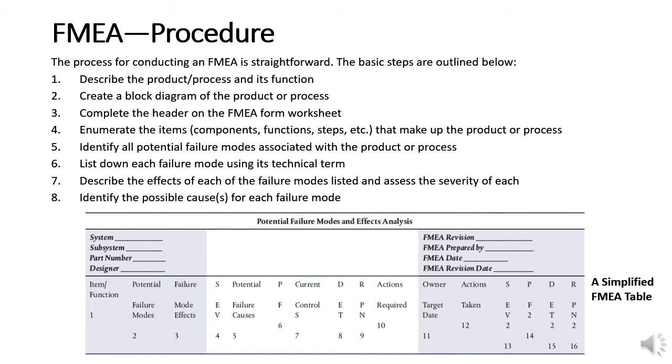A failure mode is defined as the manner in which a component, subsystem, system, process, etc. could potentially fail to meet the design intent. Examples of potential failure modes include corrosion, hydrogen embrittlement, electrical short or open, torque fatigue, deformation, and cracking.